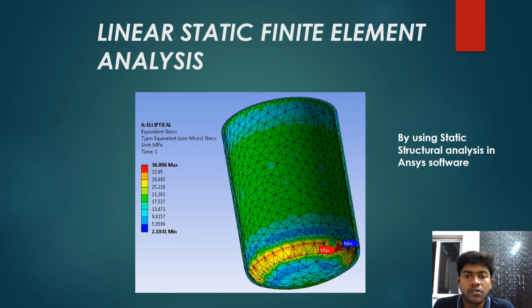So now, after constructing the 3D model of the dished heads in the Creo software, they have been revolved and constructed as a filter bowl head for a filter. And now the models have been taken into the ANSYS software, and the linear static finite element analysis is done to study the stresses on the various parts or corners of the filter bowl heads, and the screenshot of the analysis study is depicted as follows.